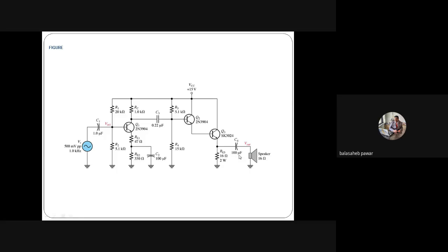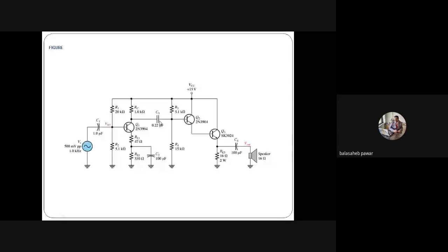So you will observe in this circuit diagram, the first stage is nothing but a CE amplifier, a simple CE amplifier, right? And by taking the actual results, we have to justify whether the shown amplifier, this first stage only up to capacitor C3, the output coupling capacitor, is working as class A, class B, class C or class AB. Okay. So whenever we implement it in Proteus, how can we justify whether the shown first stage is class A, class B, class AB or class C? Can anyone?